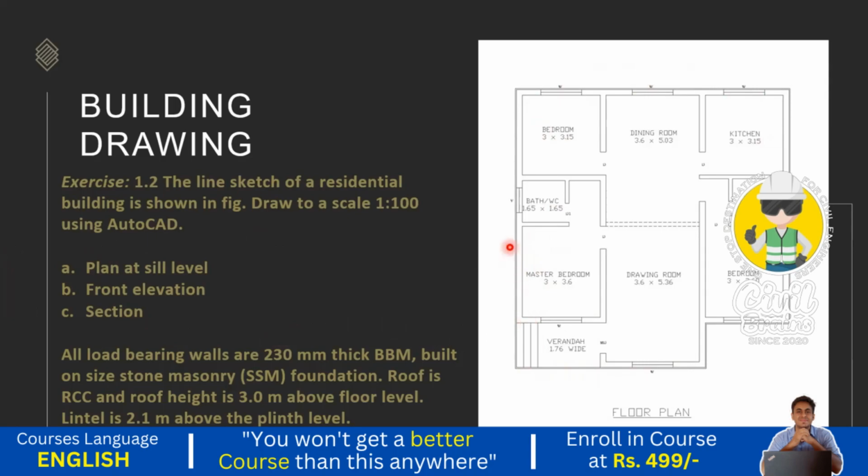About the foundation, what is the burned brick masonry? BBM in the sense burned brick masonry. It is made up of 230 mm thick, and below the burned brick masonry in the foundation is the size stone masonry we have used. The roof is RCC. Above this there is an RCC roof slab, and the roof height is 3 meter from the floor level, and the lintel is 2.1 meter above the plinth level. Clear? So this is our given question.